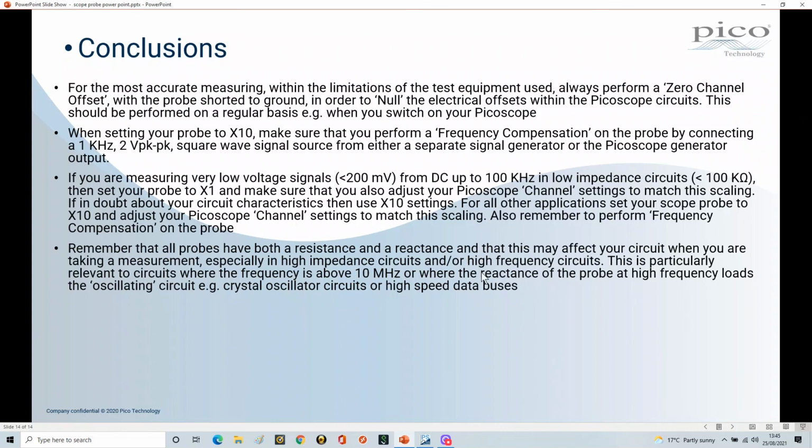This is not a problem when you're using a times 10 probe and your bus might be running at sort of like maybe, I don't know, 1 megahertz or 10 megahertz or something. But if you're trying to run something at 100 megahertz, then you've got to make sure you've got the right test equipment to be able to perform that kind of task. And you may want very special types of probes to actually monitor that to see what's going on, okay?